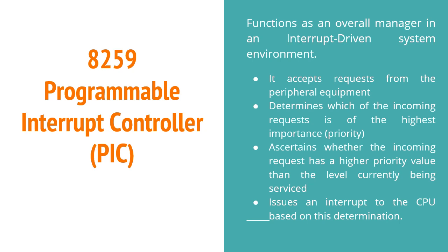First, let's see why we need a programmable interrupt controller. As we know, for 8086 there are two interrupt pins, the NMI pin and the INTR pin. But consider an application where a number of IO devices are connected with the CPU and they decide to transfer data using the interrupt driven data transfer mode. In these types of applications, we require more interrupt pins than is available in a typical microprocessor. Like in the case of 8086, as I said, there are two pins available.